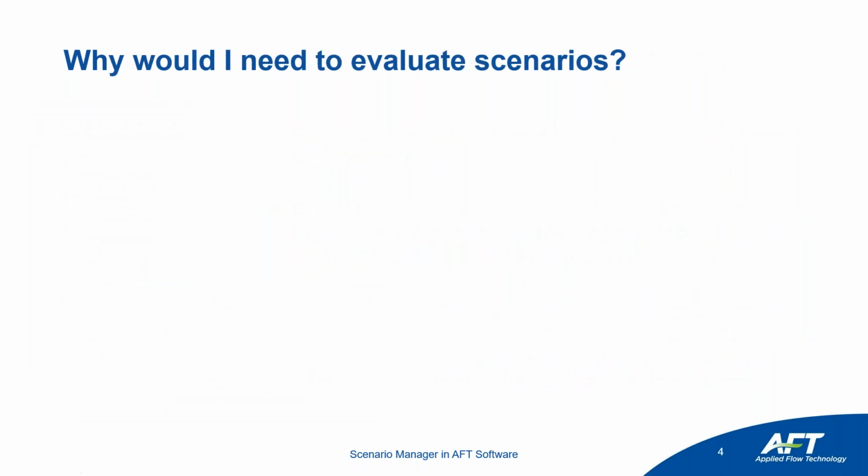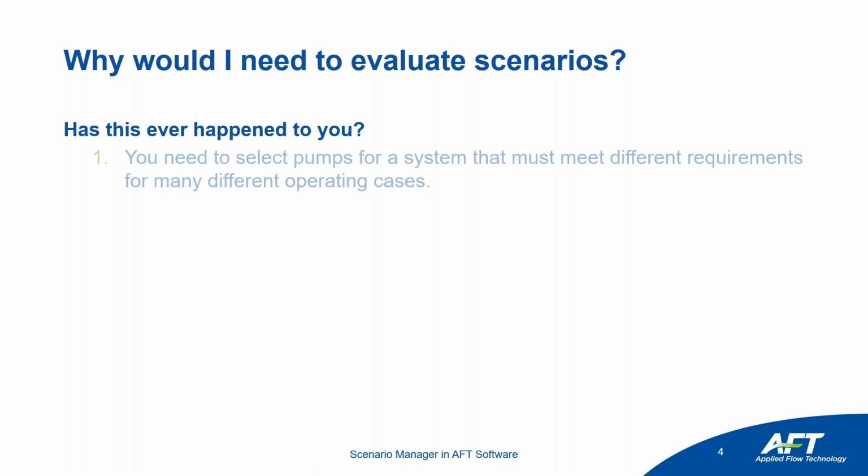So why might you need to evaluate different scenarios? You can imagine me in my best infomercial voice. Has this ever happened to you? The first case, you might need to select pumps for your system that has to meet different design requirements for your different operating cases. So you can imagine if you have different consumers or different seasonal requirements, you're only going to select a single pump that has to work in that full range of conditions. It's important that you can test each of those with that pump. Again, ensuring that it's going to meet those efficiency and reliability expectations that you have for it.